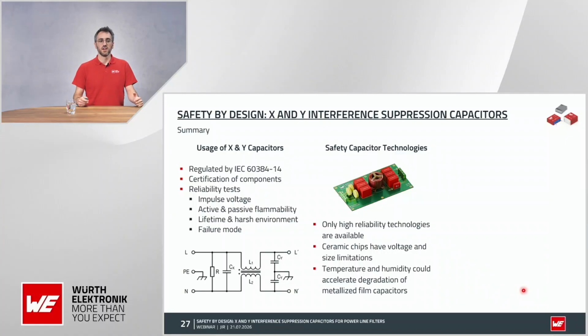We have the ceramic MLCCs with the special structure for safety, and we know now they are limited because of their size. They are limited to low voltage and low capacitance. For metallized film, we know that they are susceptible to high temperature and especially high humidity environment, which can suppose a problem in the long term.